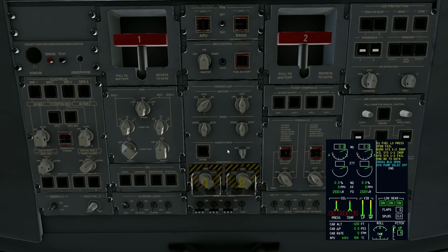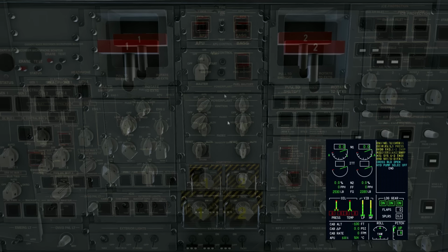And what that does is, first, it just helps the start a little bit more. Each engine has 2 FADECs, A and B, so we have a 1A and B and a 2A and B, and they command their respective ignitions. You can see from the EICAS, this letter here represents which FADEC is active. During an ignition auto start, you only use one channel of the igniter, but during an ignition on start, you use both. The reason we're doing this is so that a cold engine has a little bit more help getting started. We're less likely to get weird start-offs doing that.